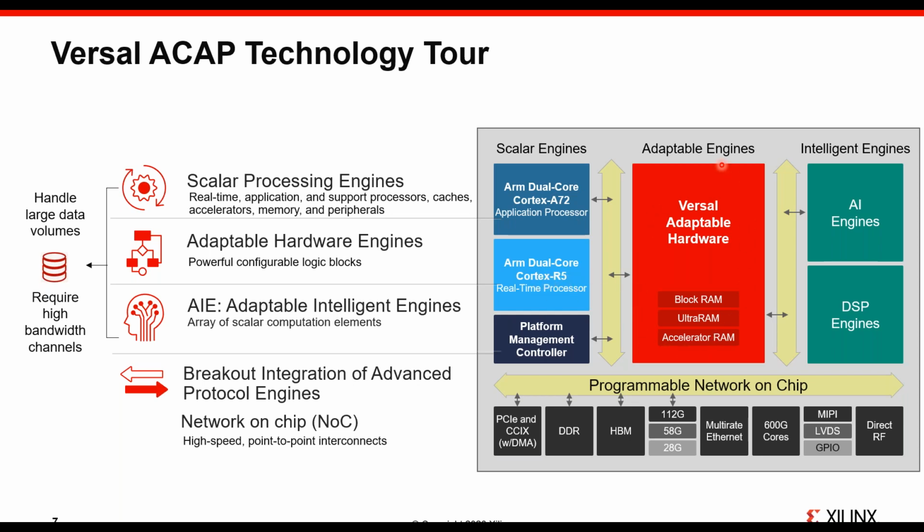You've got the general fabric, which has been the mainstay of Xilinx for almost that full 40 years. From 40 years ago, there was no block RAM or UltraRAM or some of the other macros that are involved in it. It was lookup tables and flip-flops and a carry chain, but it's so much more than that now, which turns it into an ACAP. There's also the adaptable engines.